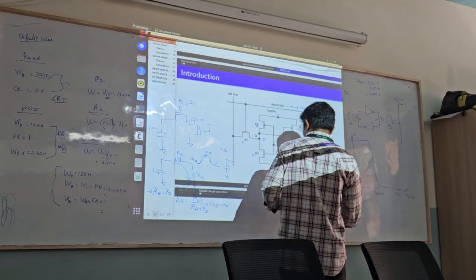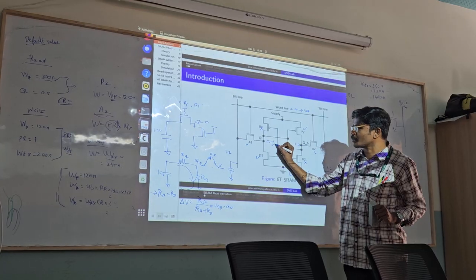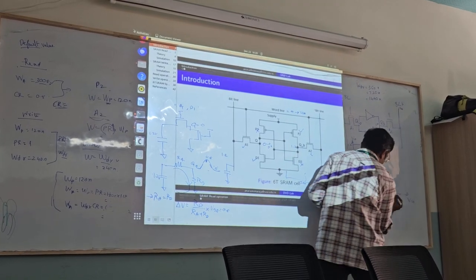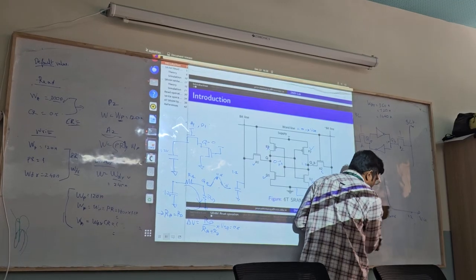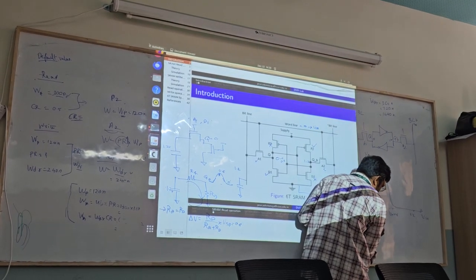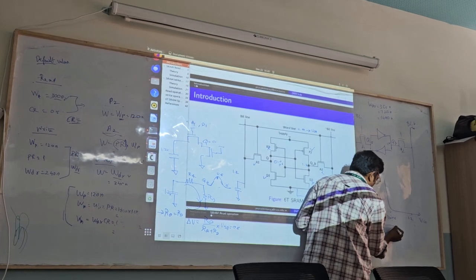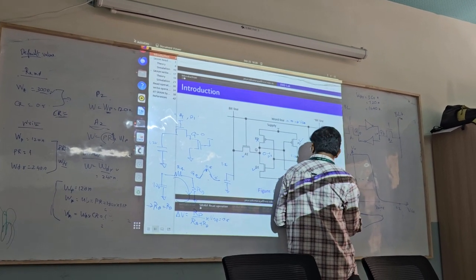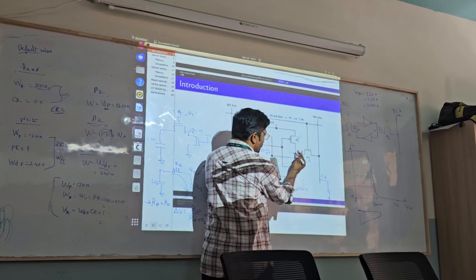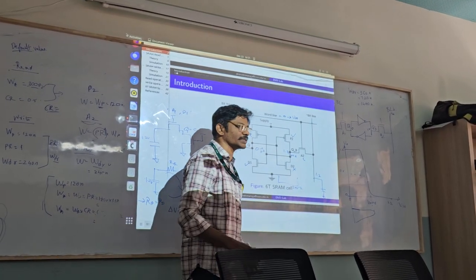Now, if this voltage is reaching all the way to 0.6, from 0 input voltage, this is my input axis, I will create a bump, and this bump goes all the way to 0.6. What does it in turn give us back? The output voltage of the second inverter is actually getting disturbed and pulled all the way to 0.6. Am I right?